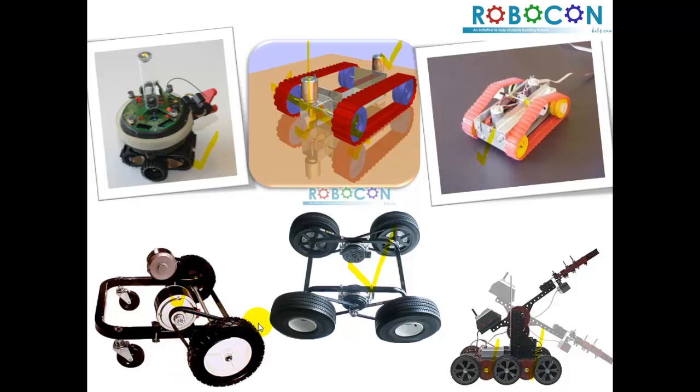If you have to transmit the motion simultaneously to the two wheels, you can use this kind of arrangement where two belts work on one single motor. Another good example of an existing model in the market is transmitting the motion via gear drive system from the rear wheel to the front wheel.